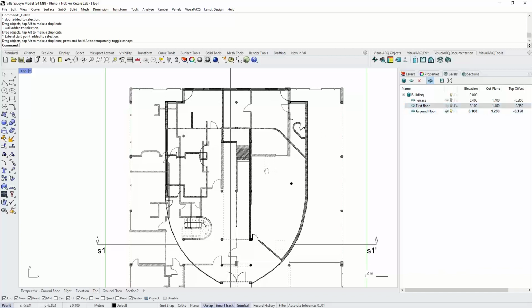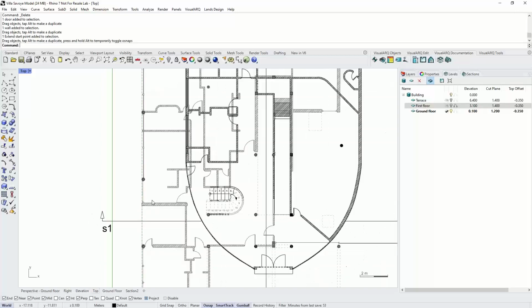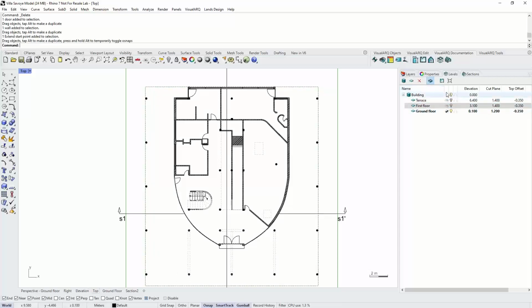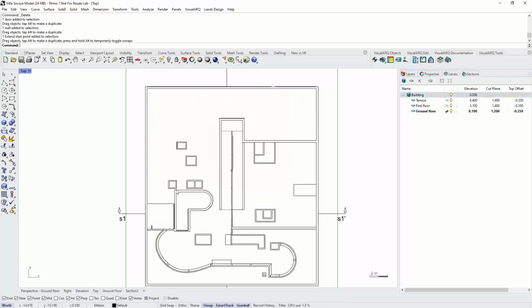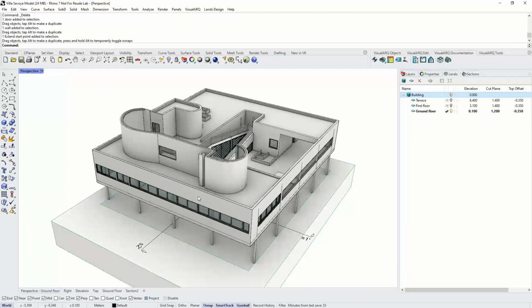This is very useful because we can see that plan view as a gray 3D representation, so we cannot select that, but we can snap on that, so we can maybe know the position of walls that we have in other levels or hidden levels, and make sure that they are aligned properly with what we construct here. Okay, so we can even project more than one level on that current floor. All right, so let's watch this in 3D again.